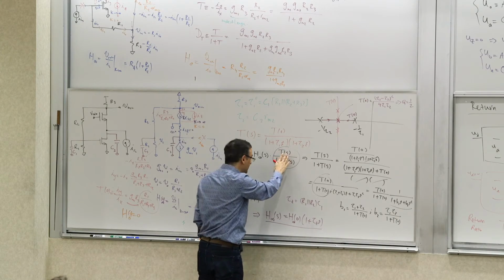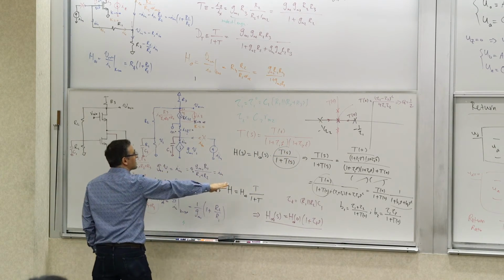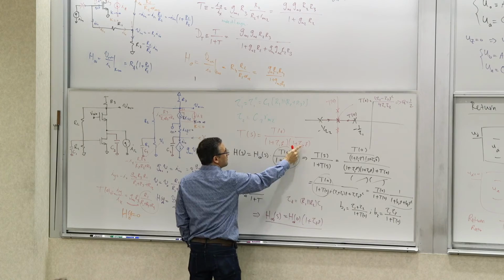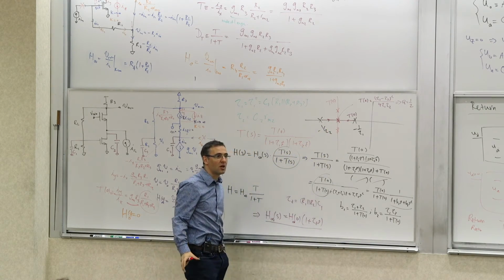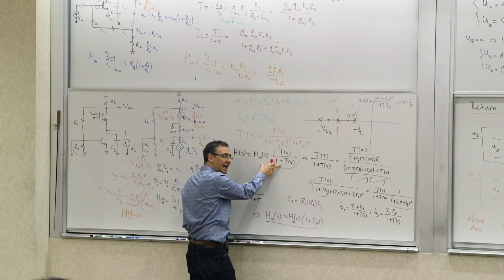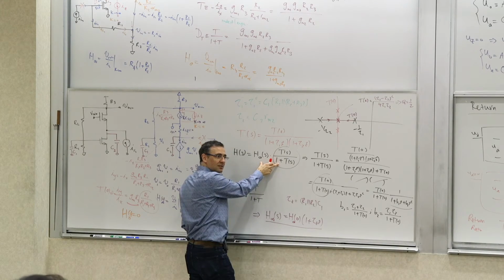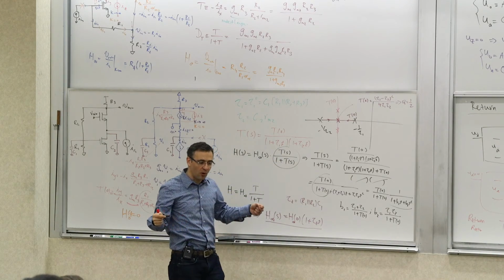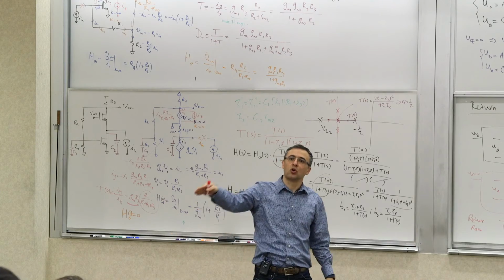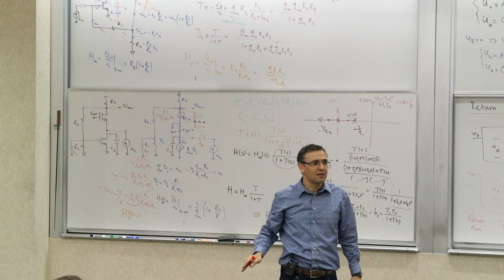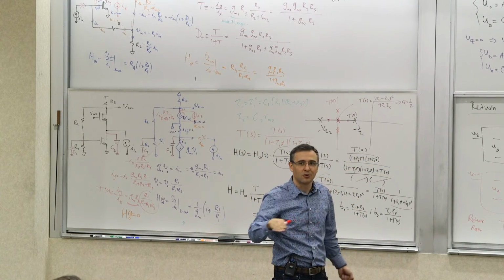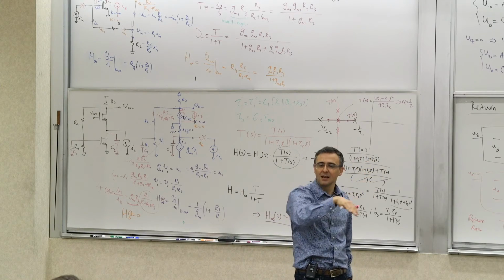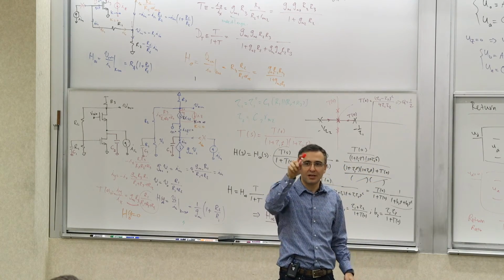The poles of the return ratio are fixed. They're at these two frequencies. These are the poles of the return ratio. But the poles of the overall transfer function go from an overdamped response, which is going to look like a slow, quiet response, to critically damped, Q of 1/2, then they become complex, and then basically you get ringing.